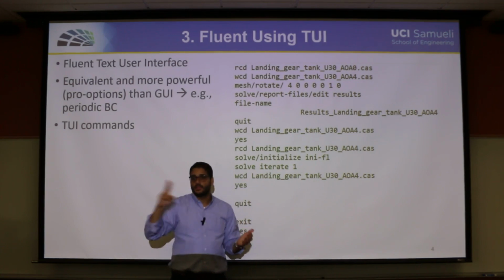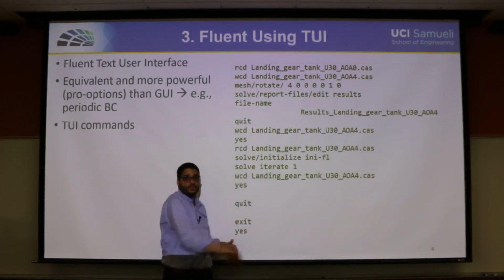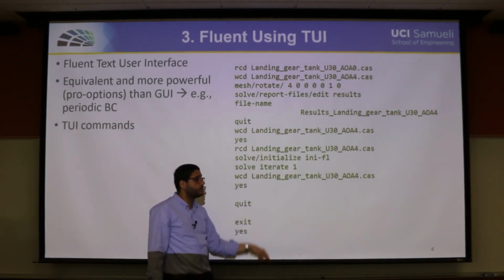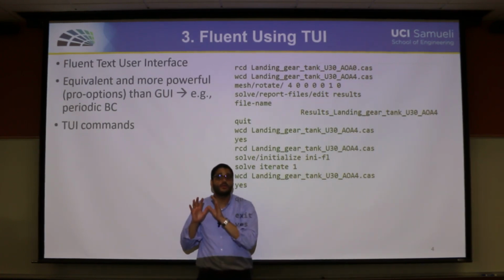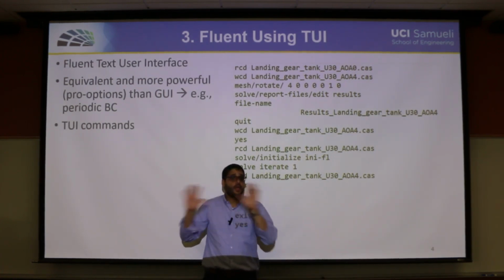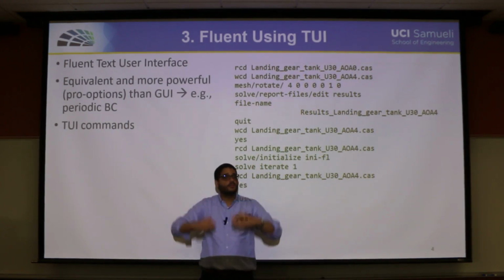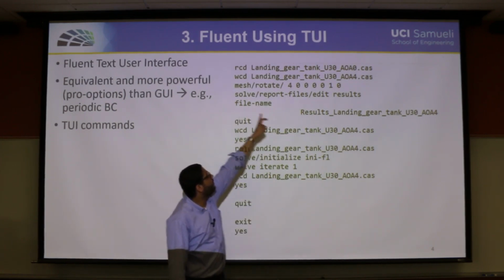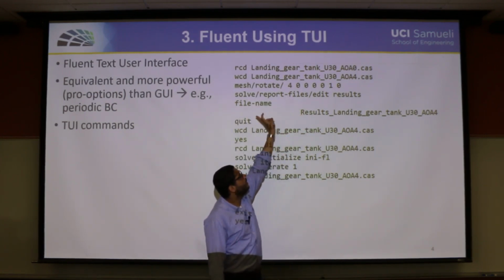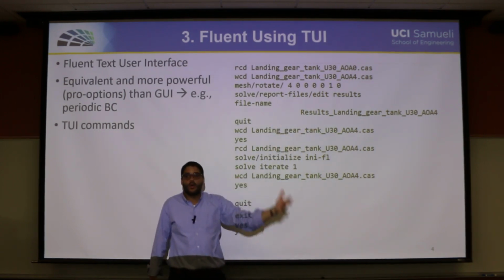However, I'm not asked to compute it at one single velocity. It was at different velocities. So I have a matrix actually. At this angle of attack, I have different velocities, and at another angle of attack, I have different velocities. So you get to choose. Either you generate the angles of attack and change the velocity, or generate the velocities and then change the angle of attacks. Even if I'm doing the simulation at the same velocity and changing the angle of attack, that will be the wiser solution.